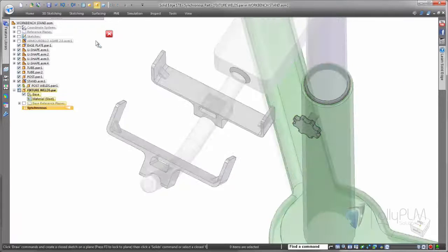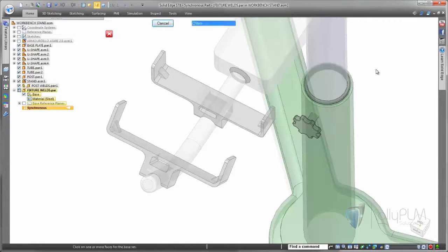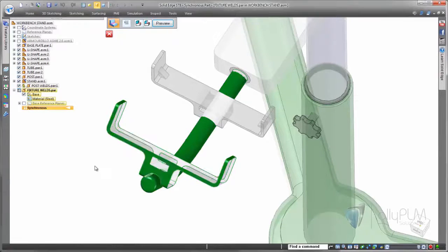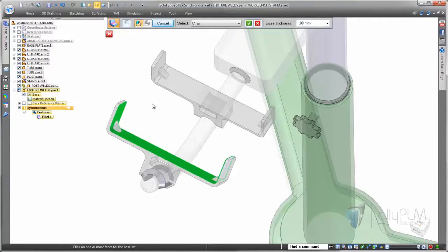This new capability gives our users a lot more control of weld bead creation through the use of standard weld bead commands, using part modeling techniques, or a combination of both. With the weld beads defined in the part environment, you have full control of the material definition, weld bead appearance, and access to their mass properties, as you'll see here in just a moment.